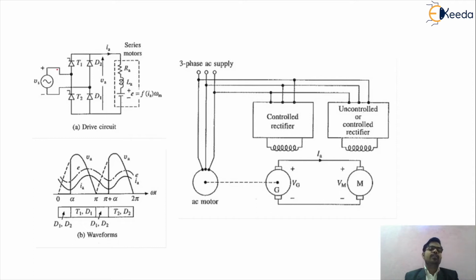Friends, we have to understand the basic block diagram of your drive. I think everyone has got a clear idea. There are different blocks present in that particular system: source, power modulator, motor, load, sensing unit and control unit. This whole combination is treated as a drive. And friends, it is a series drive, so we are using the series motor. For that we use some type of power modulator, because with the help of power electronic devices itself we have to control the motor.